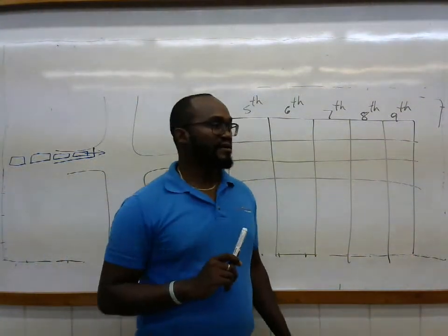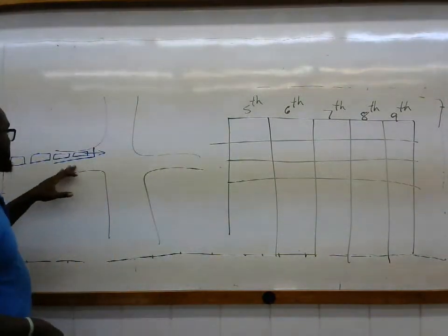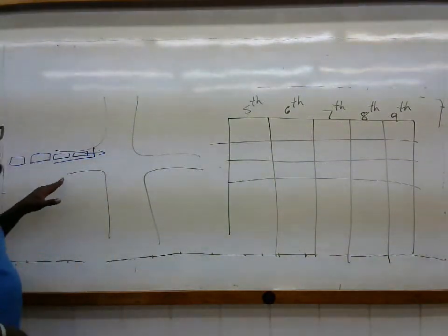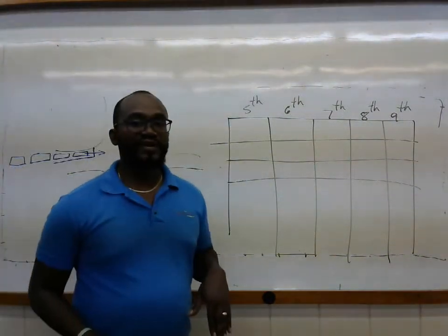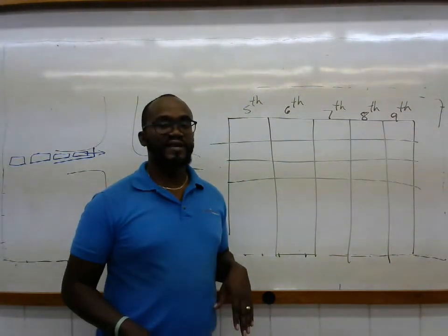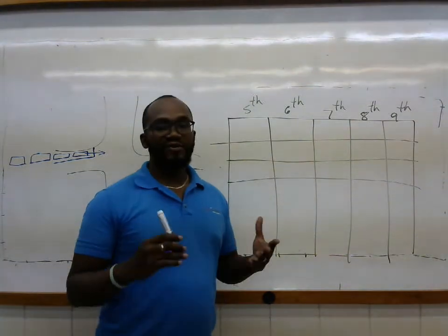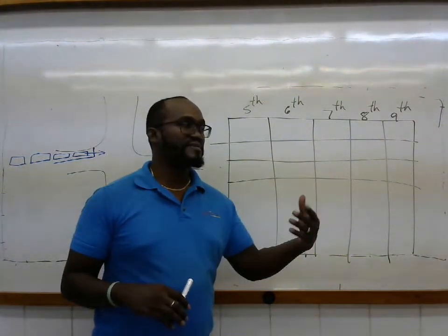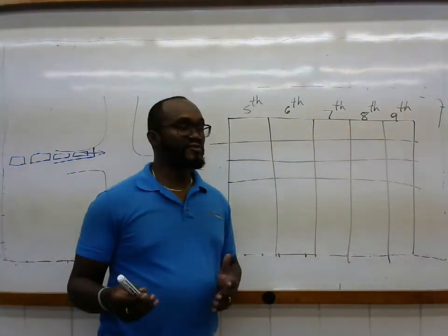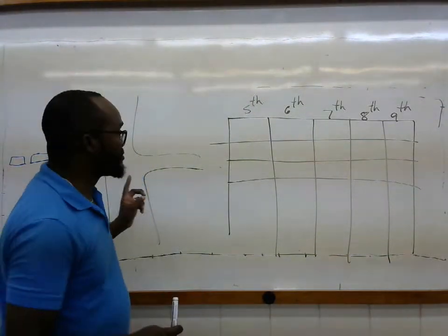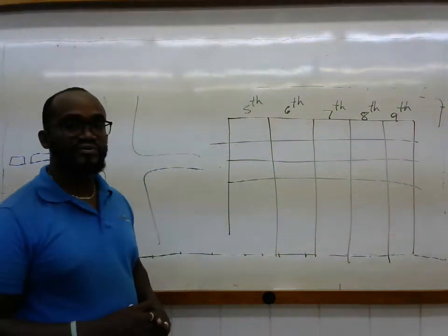That's why, in theory, after the fourth vehicle passes, it is assumed that the vehicles are moving at constant speed or at the desired speed in the traffic stream. Of course, practically that may not happen due to obstacles downstream, etc., but for the most part, that is typically so.